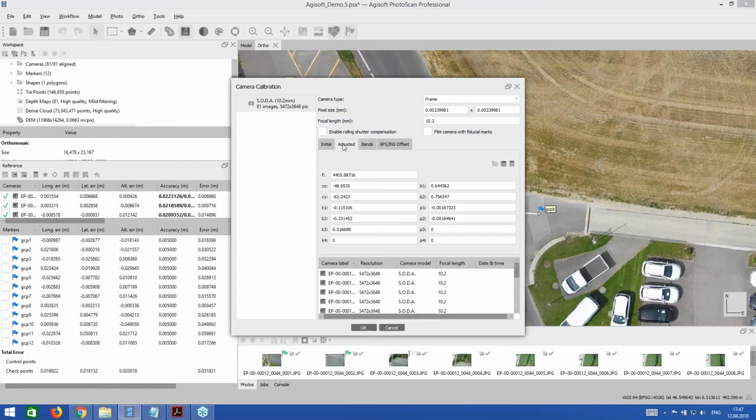One is georeferencing based only on onboard GPS, and in this case, the precision will be comparable to the accuracy of the coordinate measurement. So it could be several meters, for example, for simple consumer-grade drones. However, even with a low accuracy onboard GPS device, you can always use control points to improve the accuracy of the result.